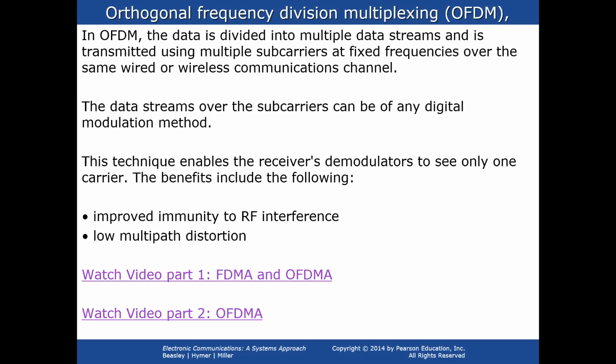Suppose we have 8 bits of data to be transmitted using QPSK modulation. The data will be divided into 4 parallel streams of 2 bits. Phase and amplitude assignment is done according to the QPSK constellation. Finally, data is placed over the resource elements by adjusting the phase and amplitude of the subcarrier to those derived for the data stream. Mathematically, it means multiplying the complex modulation symbol to the corresponding subcarrier frequency.